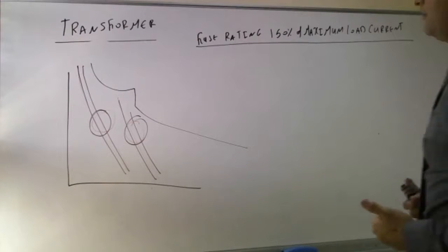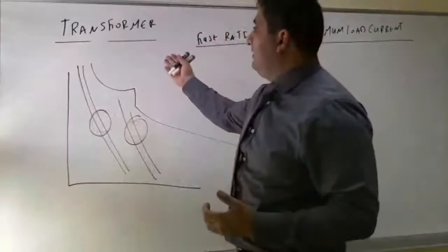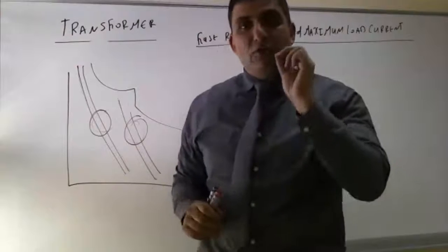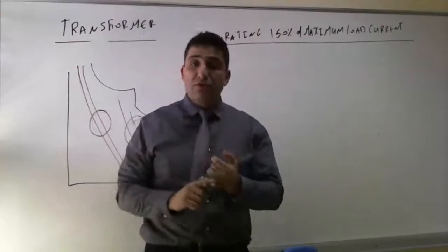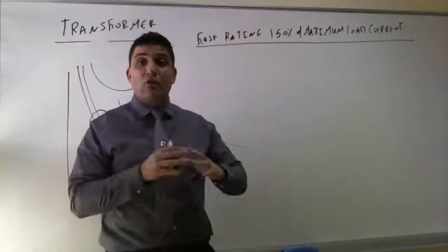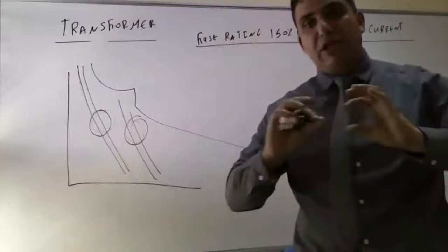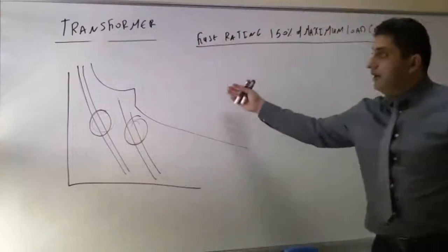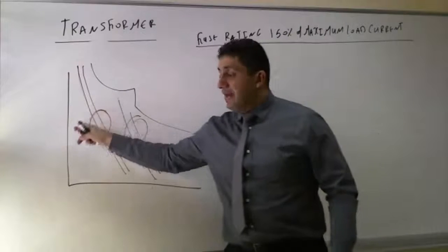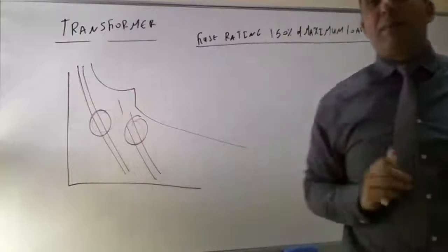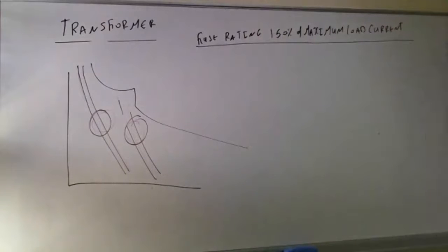So to conclude, to design a fuse for a transformer below 2500 kVA that is not located in a special location, which means I am allowed to use a fuse as protection, I need to make sure the rating of the fuse is within the transformer fault capability. I hope that's very clear to you guys.